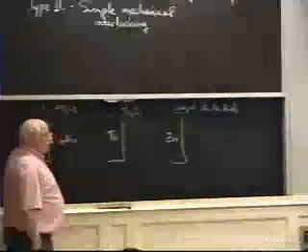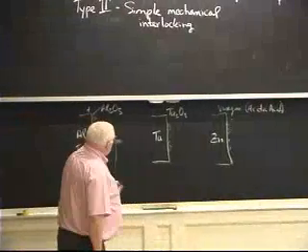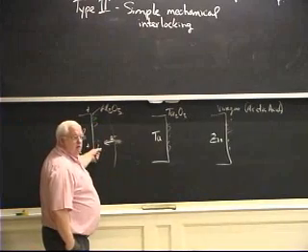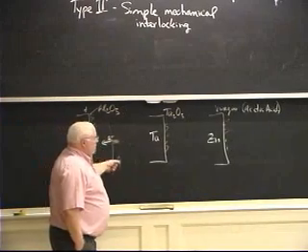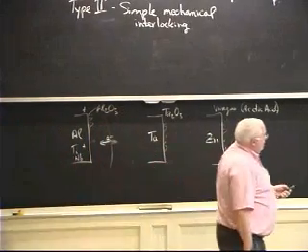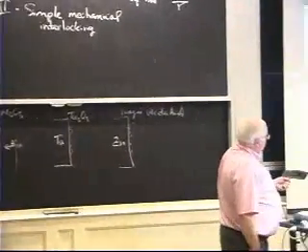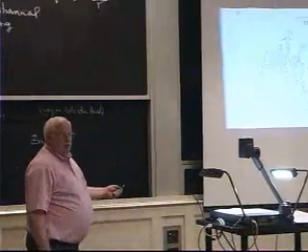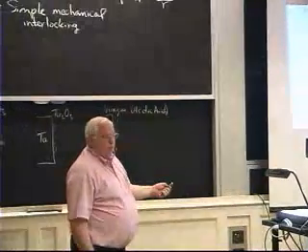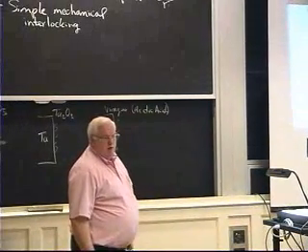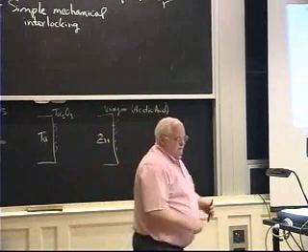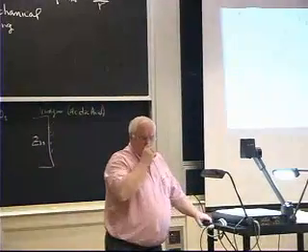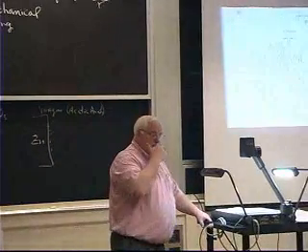If you're going to do adhesive bonding, you want this type of structure, and you can either put the adhesive on here or you can put paint on here, and the stuff sticks. You can do it with tantalum if you're trying to paint tantalum. I don't know why you paint tantalum, but if you're trying to make a capacitor. If you want corrosion resistance, you better seal it by filling it up with a paint or polymer, or you can grow the aluminum oxide by just boiling it in water for an hour or so, and the aluminum oxide will grow in between.